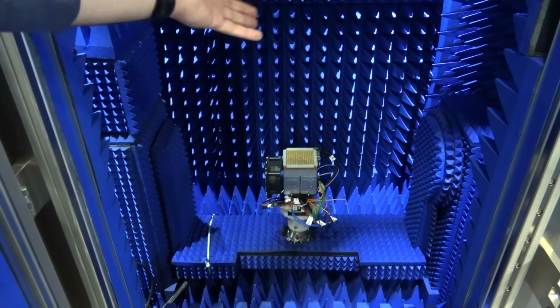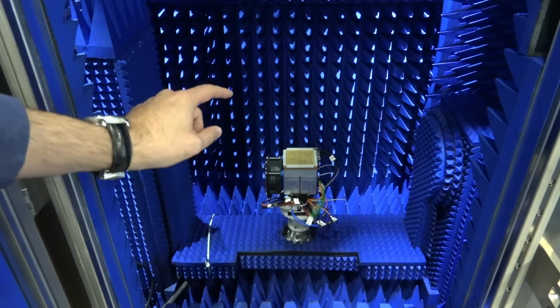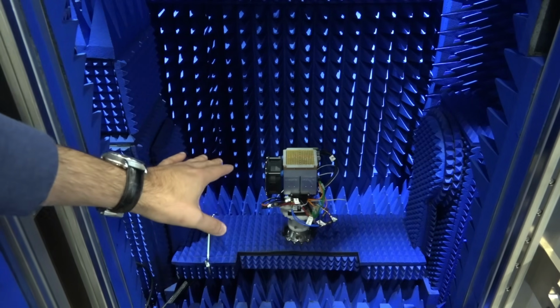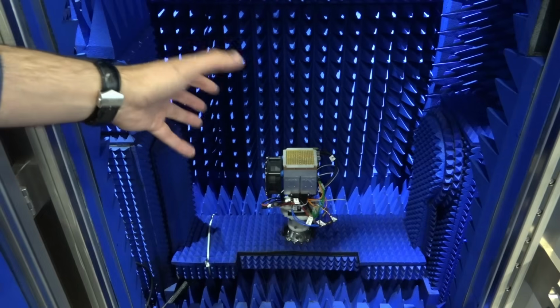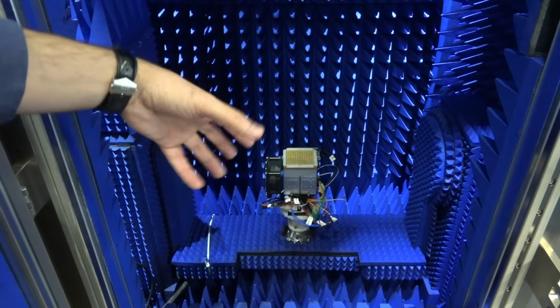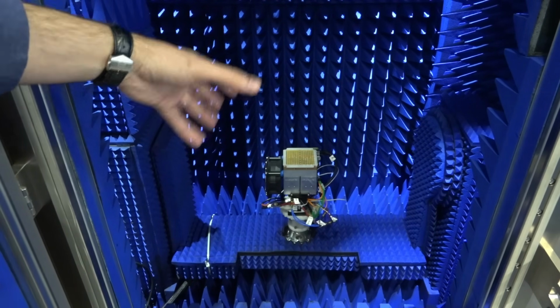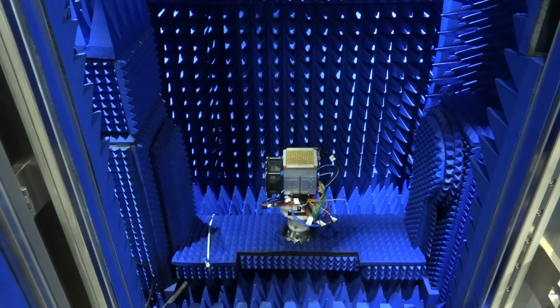Then you can steer the beam, just like any phased array would. And as you steer the beam, you will see all of the imperfections of the beam. You can get ERP over the angle. You can find out what happens to the power. Now, because you're looking at the measurement plane of the device, you can also do things like DPD. You can find the nonlinearity of the device, but you're measuring it in far field. So you're measuring the nonlinearity of a phased array, which is subject to a lot of active return loss and unknown things that happen in open space. You're capturing all that in one go inside of the chamber.